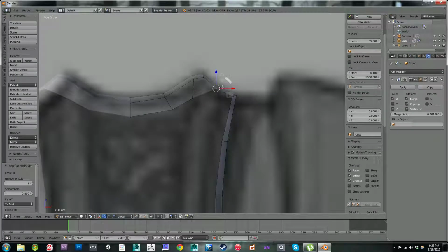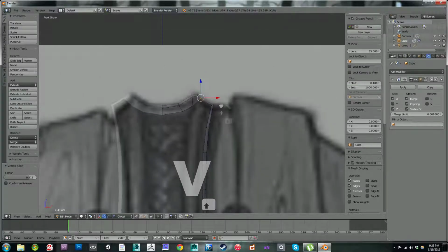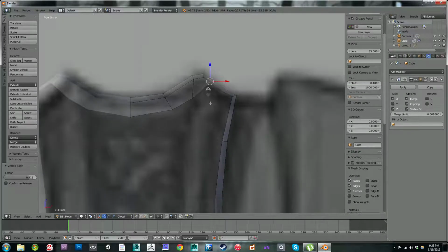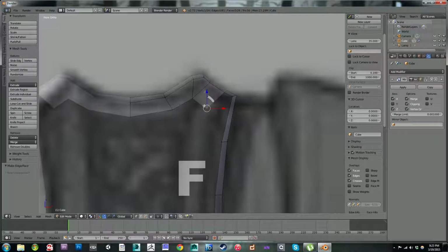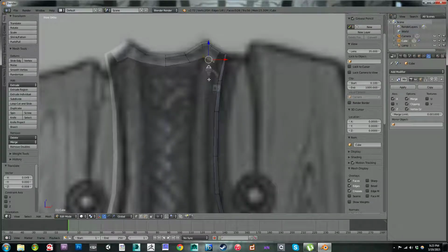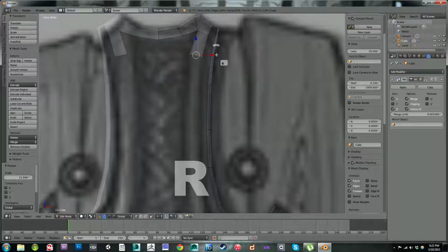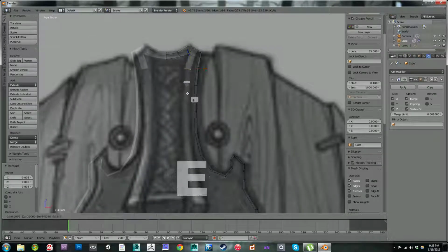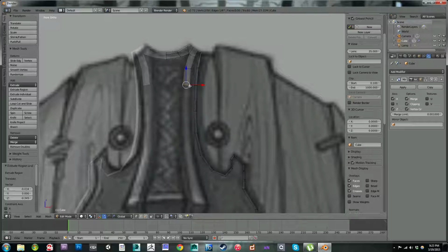But that way I can shift this up and I can have a path to start creating that face. So let's start to shape that out. And now I'm going to not use F2 here. I'm just going to position that and then start to follow that edge and make this. And again, I'm trying to eyeball to keep it in line with these other edges I've got on here.